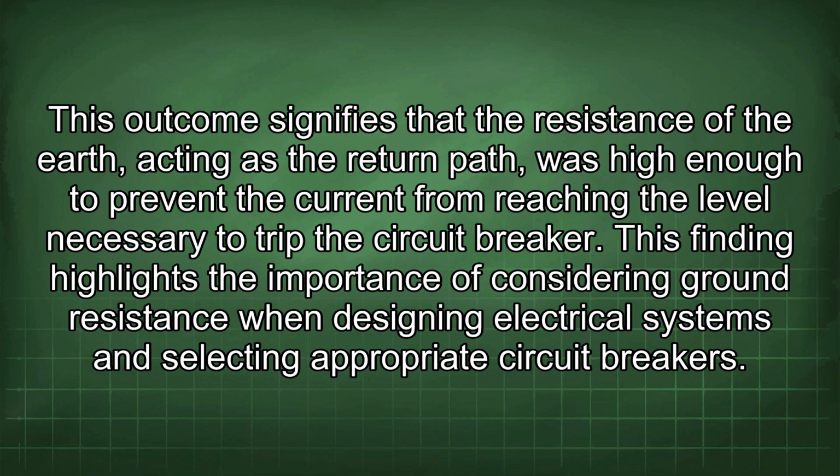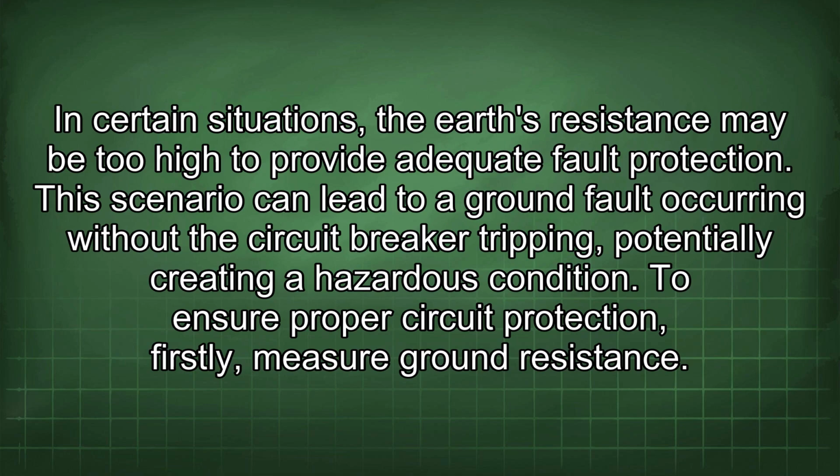This finding highlights the importance of considering ground resistance when designing electrical systems and selecting appropriate circuit breakers. In certain situations, the Earth's resistance may be too high to provide adequate fault protection. This scenario can lead to a ground fault occurring without the circuit breaker tripping, potentially creating a hazardous condition.